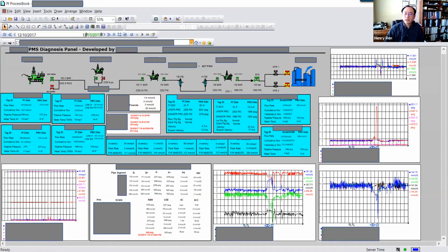Now, in here, as I said, the platform has instruments, but it comes down to this is all subsea pipeline, subsea network. You don't have instruments at all. And even the instrument here is not reliable, okay? And if you include those in the model, the model will be upset, okay? So we just use them for comparison, all right? But in here, we see the model calculation, you can see a lot of difference, okay? Those instruments are not tuned properly, so that's the reason.